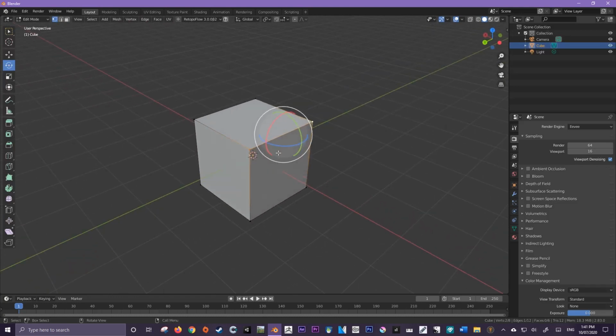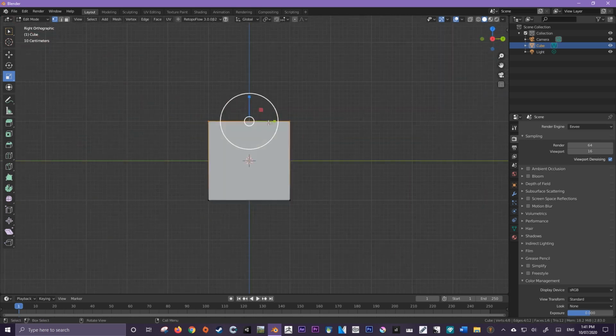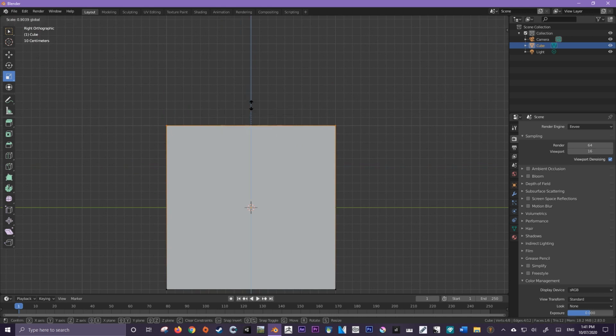So sometimes similar things can happen with our scale tool too. If I grab my scale tool and I select a face like this, which direction do you think, if I scale in, nothing will occur? If you think it's the Z direction, you are absolutely correct. So let's now do this. So scaling on Z and nothing's happening.